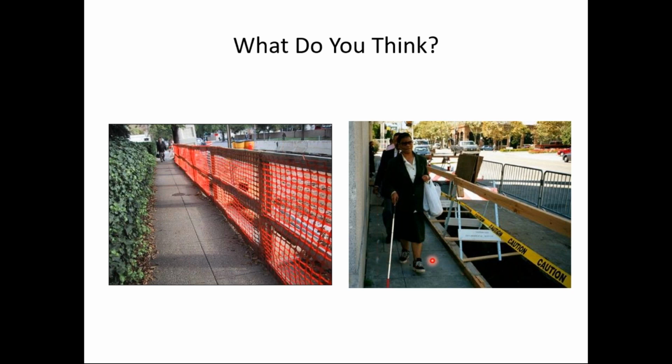So we have a 5-foot walkway, which complies with PROAG. We have an 8-inch sort of toe board down here, which complies with the edging requirement. There's also an upper rail. And so to me, this would comply with PROAG. But I use this example to illustrate that PROAG is an accessibility standard. It's not a safety standard. We still have to use our training, our education, our knowledge, our experience to build safety into these projects.